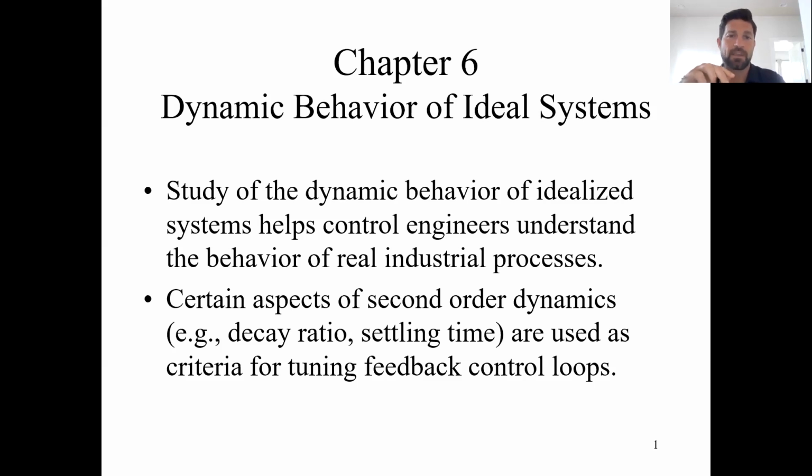Okay, so we're always going to be looking at the response to a step change in the input. Just to give you a little bit of an overview, we're primarily going to look at maybe only 4 or 5 different types of transfer functions, and based on those we can sketch the dynamic response. And by saying 4 or 5, it's really more like 2 with slight differences to them.